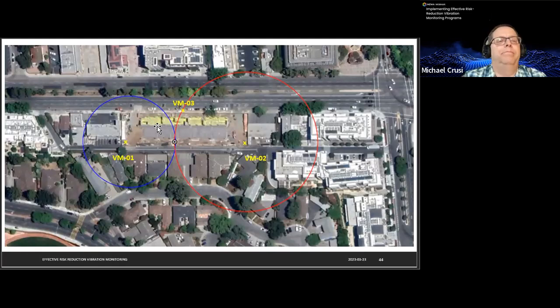Sorry. So here our project site abuts these existing commercial structures. If there are cracks in the walls, those are going to be pretty obvious, and those would be things that would be fairly straightforward for you to put some crack monitors on to see if things are shifting and moving. The residential structures might be a little more difficult because there's an alleyway, and these structures are not directly abutting our project site over here.